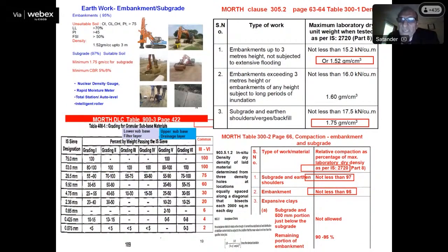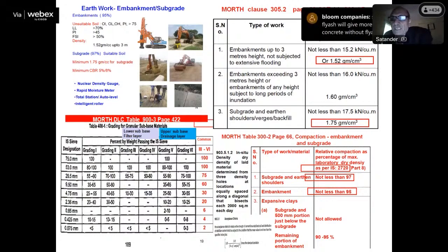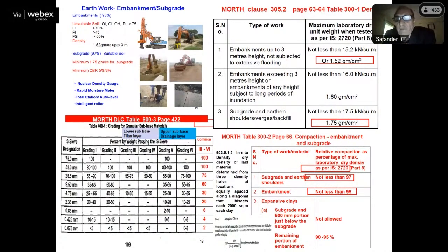I think all this you may be knowing, I am skipping. Fly ash will give more strength than concrete without fly ash particles. I fully agree with fly ash, strength will be more, but after 90 days. You will get better strength after 90 days, not before. You have to compromise. That is why in all PMGSY roads, we have suggested design for 90 days. In the case of bridges, 35% is allowed. In the case of concrete road, 20%. Now they have increased it up to 25% also. So these are the specifications already. I think everyone might be knowing.